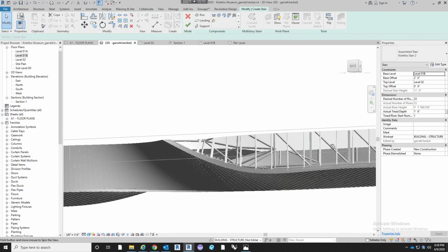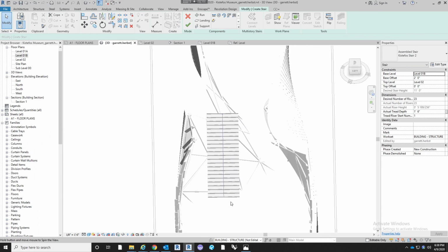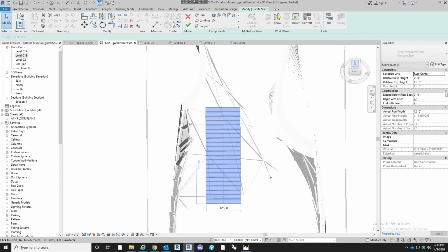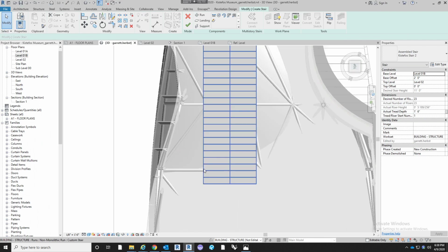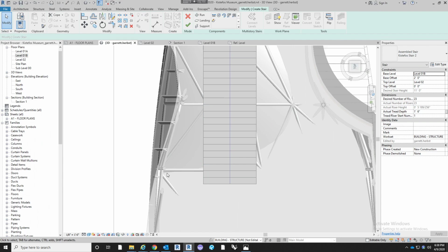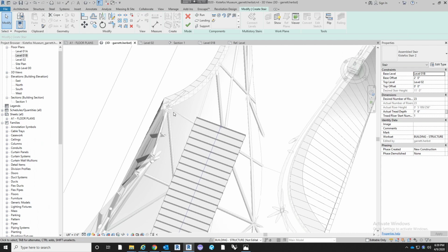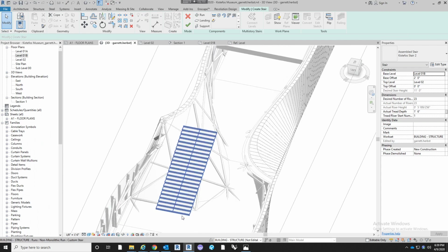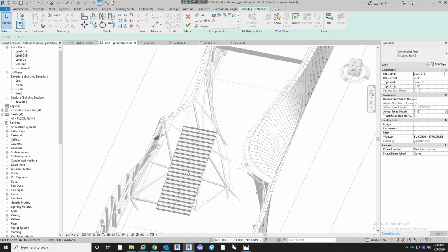No, that's about right. Alright. So what we're going to do is manipulate this stair so that the treads go out and have a custom profile that matches the outside edge of this guy right here, and then also bring the edge of this guy around and have them wrap and kind of tuck underneath just like they do in the concept image.